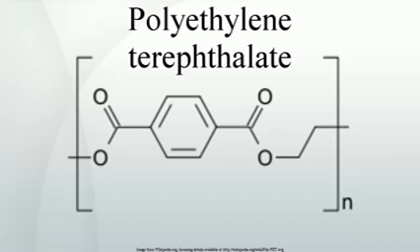In particular, increase of COOH end groups, increase of color number B, increase of haze in transparent products, increase of oligomer content, reduction in filterability, increase of byproducts content such as acetaldehyde, formaldehyde, increase of extractable foreign contaminants, decrease in color L, decrease of intrinsic viscosity or dynamic viscosity, decrease of crystallization temperature and increase of crystallization speed, decrease of the mechanical properties like tensile strength, elongation at break or elastic modulus, broadening of molecular weight distribution.